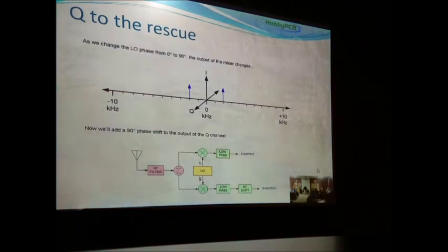So if you take their 20 megahertz of spectrum that normally is a single TV signal, and you put the 40 meter band into it, with a dynamic range with thunder crashes of something near 140 dB, it just is not going to work very well. It looks like it's working, and if you use it on the bench and you don't put in too loud or too soft signals, it runs with all the software. But I can't even imagine what it would look like on an afternoon when the band is really active on 40 or 20 meters.